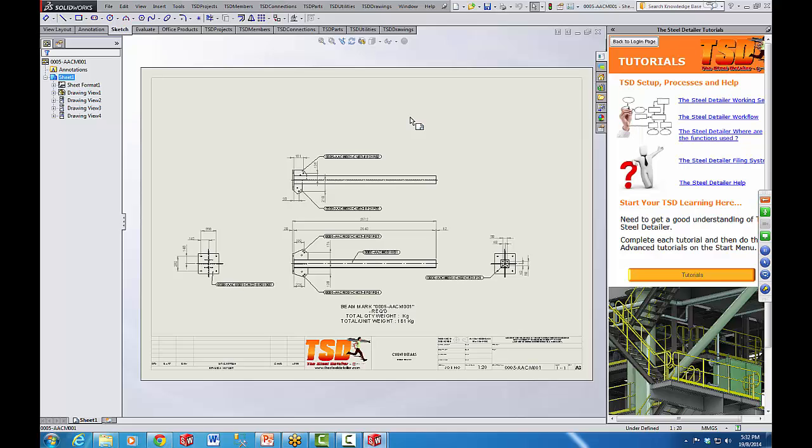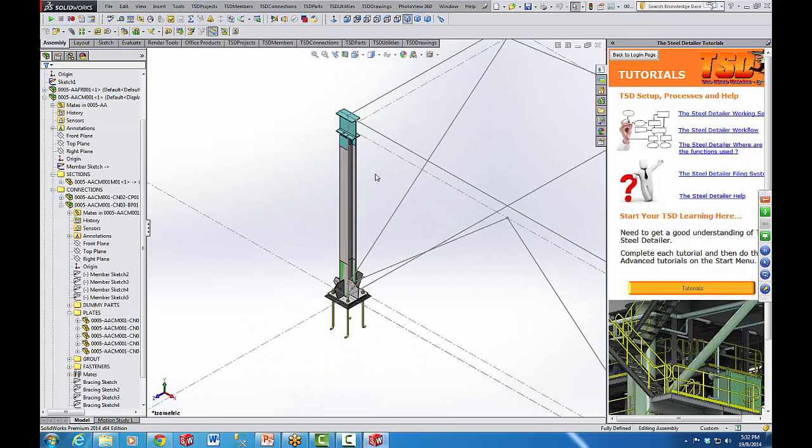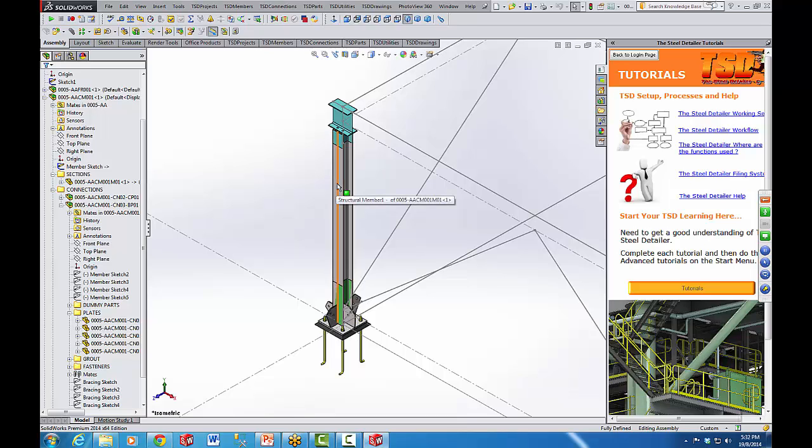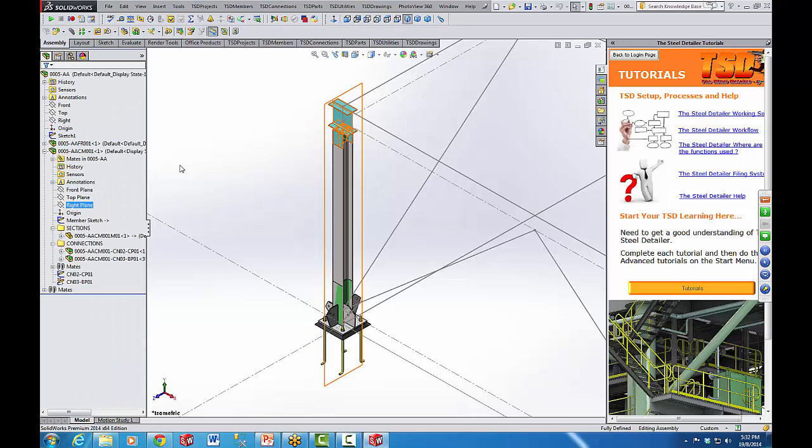So when you go through setting up your project and you model your project, this is the template phase. When you go into the locking process, it will consolidate everything except for your members. It'll consolidate plates and sections. Okay, the reason it doesn't do members is because we use the members in our general arrangements, and we want to use that information by setting up notes and all that sort of stuff. We'll cover that in another educational process. Okay, so this column now pretty much is ready for us to lock.